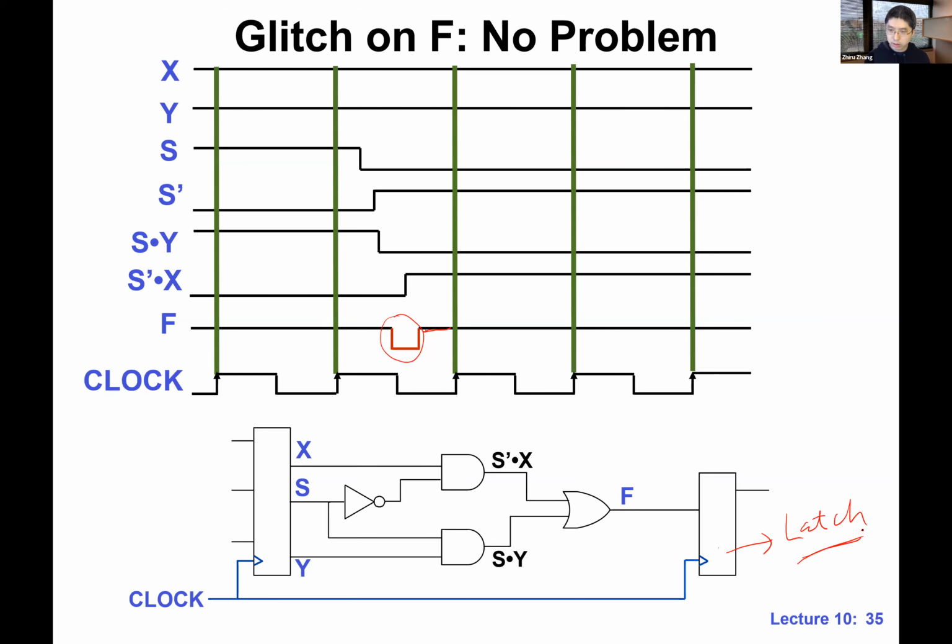Okay, very good, guys. Because this latch may connect to other computer logic, to other parts of the system. So the moment that a glitch is captured by a latch, this error may propagate, and this may be out of control eventually. Very good discussion. Emily, you're basically saying the same thing. There could be additional logic connecting to this latch, and the moment we capture that, since it's level sensitive, it's going to propagate.